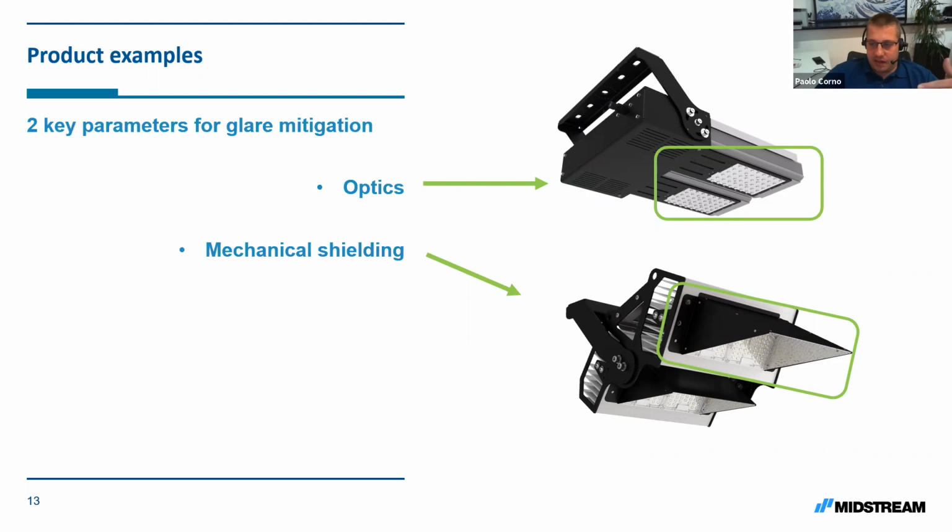By using an optic matrix like this, not only do we extend the emitting surface, reducing the luminance of the source, but by giving it this asymmetric shape we are also able to reduce the peaks of the light in terms of candela per kilolumen, reducing again the veiling luminance in the hotspots. So it gives a smoother, more uniform type of lighting, and at the same time it lowers your glare value. We will see a comparison between the use of an asymmetric optic and a symmetric optic with the same flux on a scenario shortly.